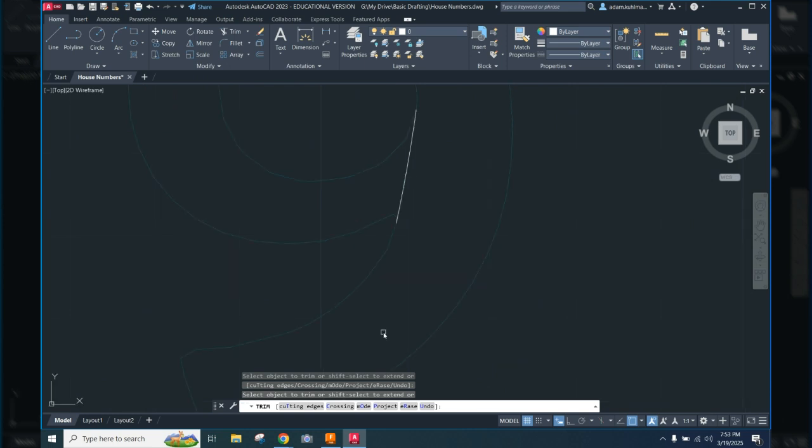So I think that's going to look okay. Now what I'm going to do is use the offset, and I'm going to specify a distance down here. We want to have our supports at least a 1/4 inch thick. We could go up to a 1/2 inch. I'm going to go 0.5 for a 1/2 inch. And so then I'm going to pick this one, and I'll slide my arc over here.